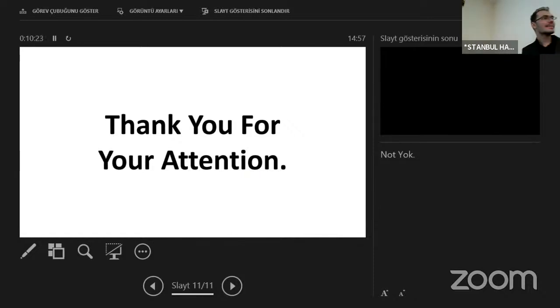You tested megahertz up to several gigahertz, but only used one 16 megahertz test. We made two tests. One is the conducted emission, one is the radiated emission. The conducted emission test starts at 9 kilohertz to 30 megahertz. But the radiated emission test started at 30 megahertz and finished at 1 gigahertz, but it can be tested at upper frequencies. Thank you.